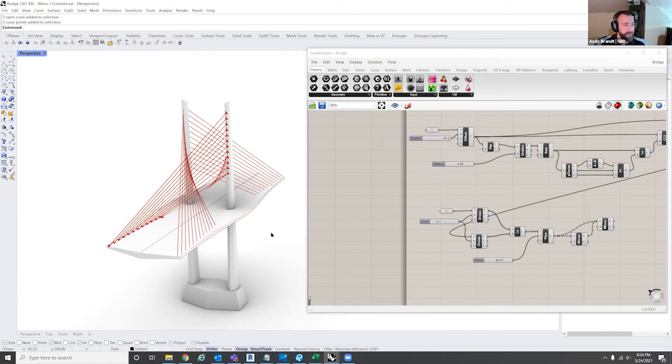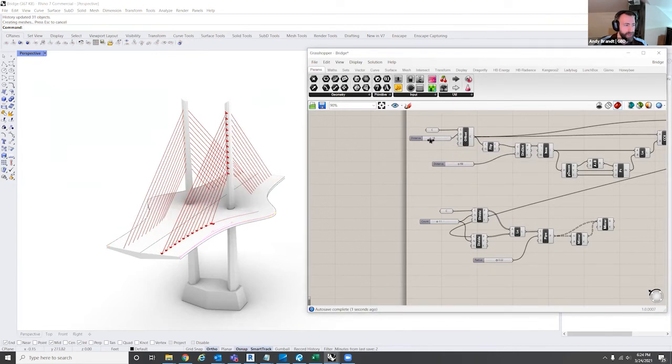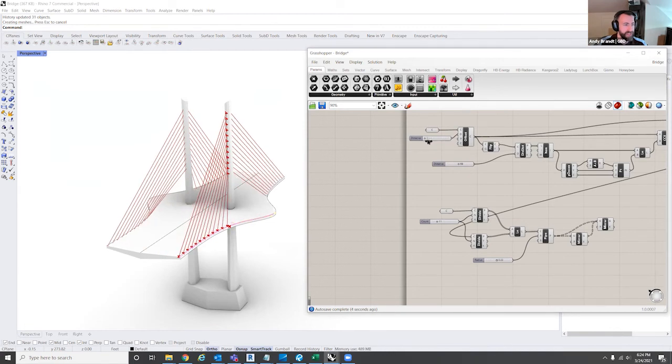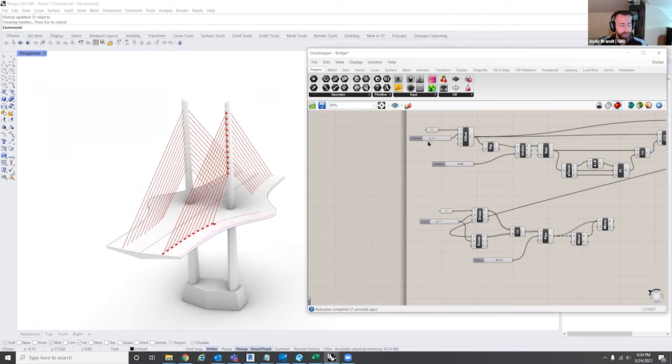And all of this is really based off of this one magenta line. If I grab these 2 control points and pull them over, the rest of it is all mirrored and offset, and the curve of the cables is based off of that offset as well. We might not be doing bridges, but talking through the mental approach to these things, all of a sudden I can do a very quick mock-up to get to the client